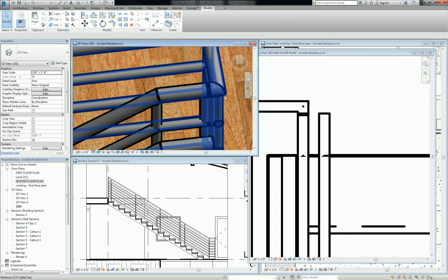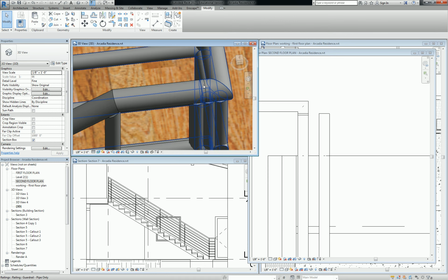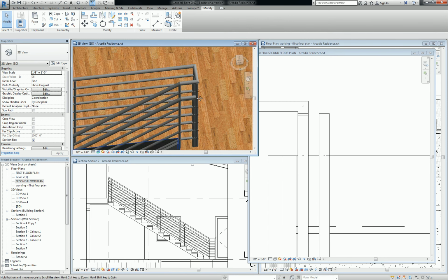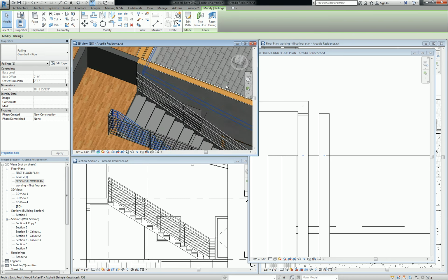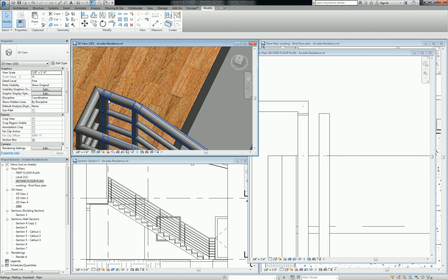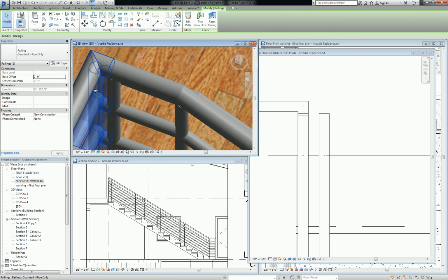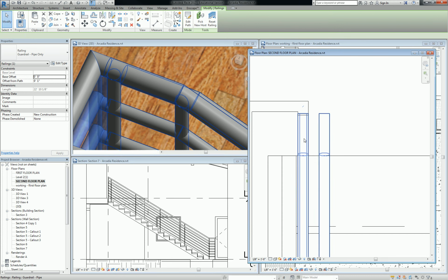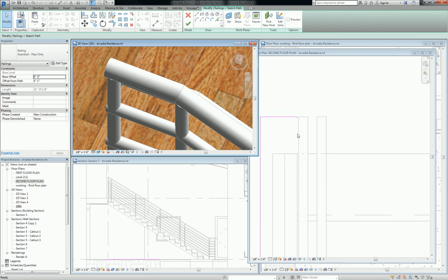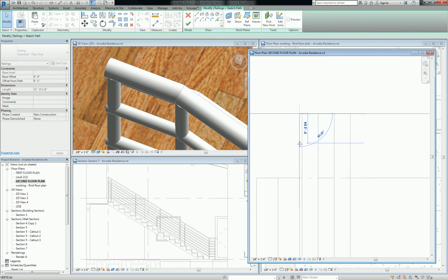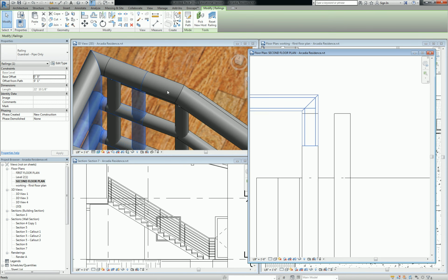Now it's not perfect, right? If you look at it really closely, there's an overlap, but it's the best you can do with a Revit family. Additionally, part of the complication is that this corner piece creates a post at both ends. So you're creating 3 posts here, right? You have the post for that 1/4 inch offset. And I guess what you could do is edit the path and extend it a little bit to try to get them to sync up, but I don't know exactly how far back that other post is.